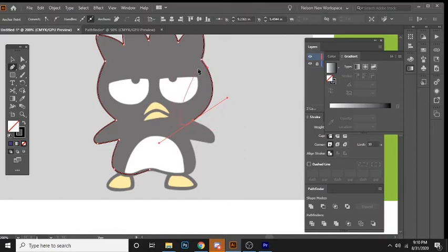I recommend using few points. The fewer the points you use, the cleaner your drawing is going to be, and the easier it is to make changes. And another tip of advice, whenever you're drawing a curve, all you need is 2 points. Sometimes I'll see people use about 5 points to make a curve, but all you need is 2 points to make a curve.